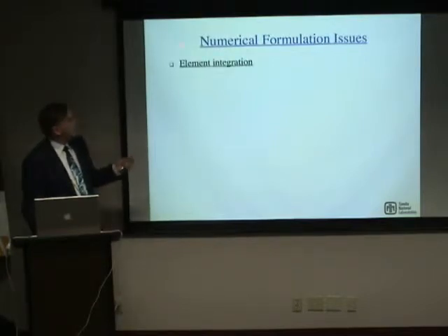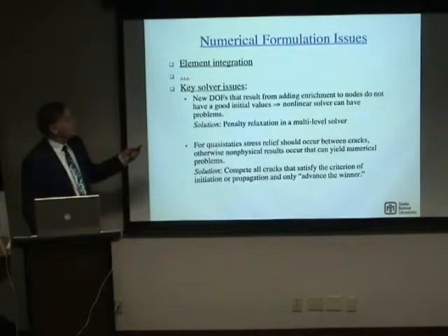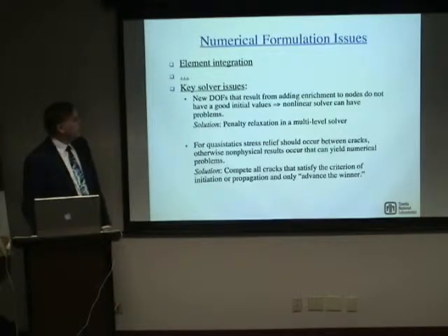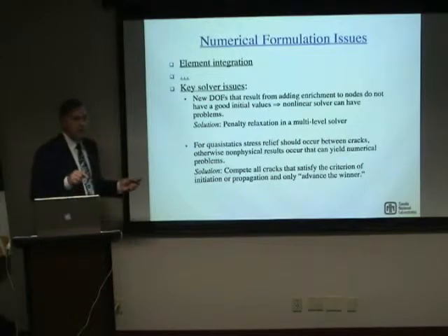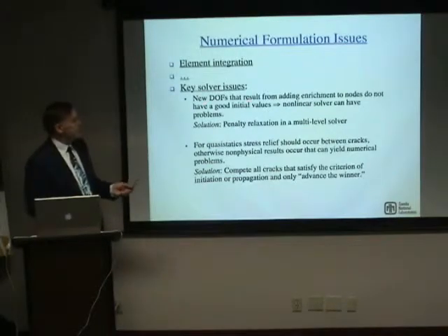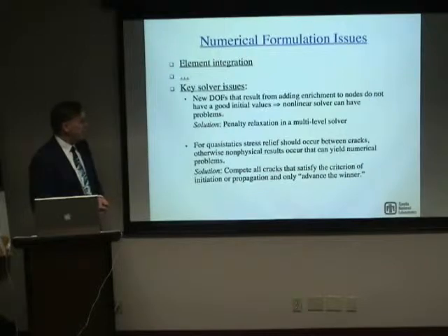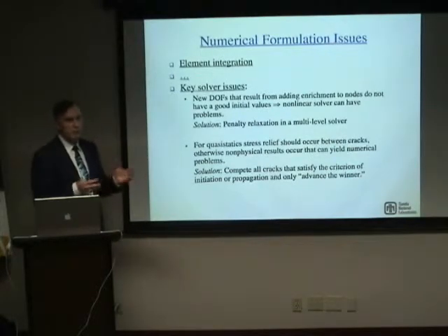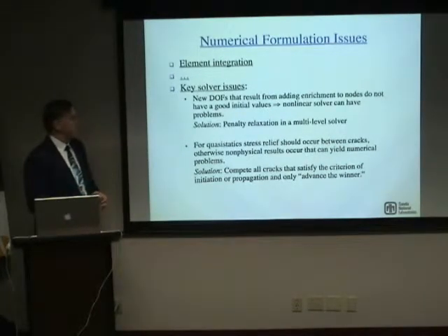Now there are many issues in the numerical formulation. We'll skip them today for the most part. I'm going to mention a couple related to the solver. One is that as we're adding this enrichment with the crack propagation, we're adding new degrees of freedom on the fly. The problem is they don't have good initial values because they didn't exist before. And so the nonlinear solver can tend to croak on this type of thing. I've had cases where these new degrees of freedom just completely ruin your convergence until eventually, based on the parameters you put in, it'll say it can't get there.